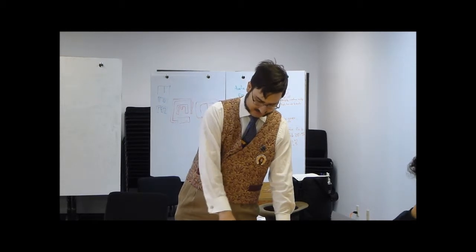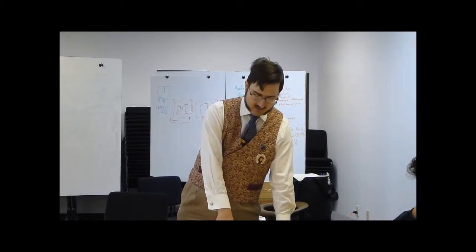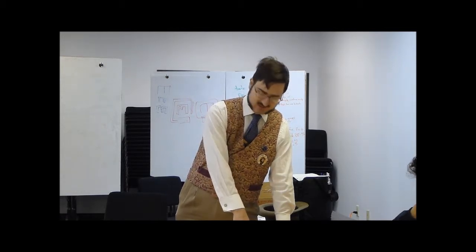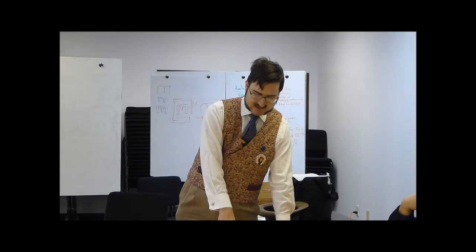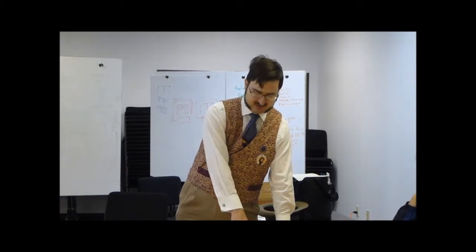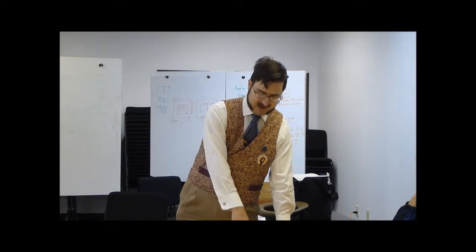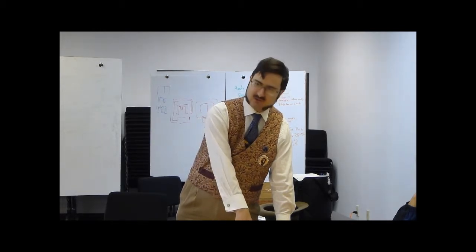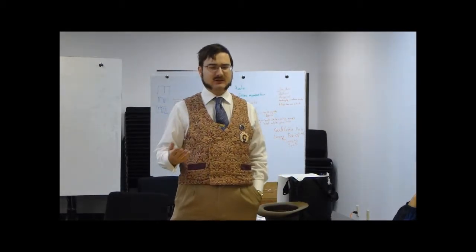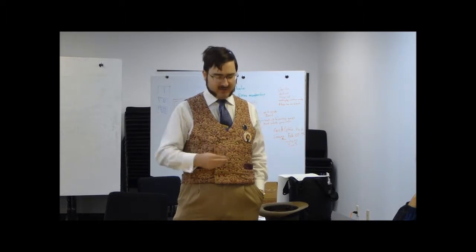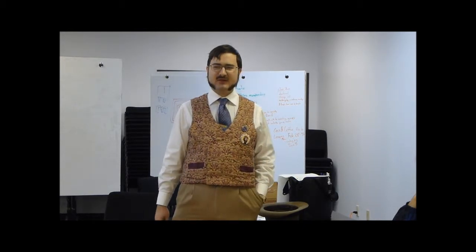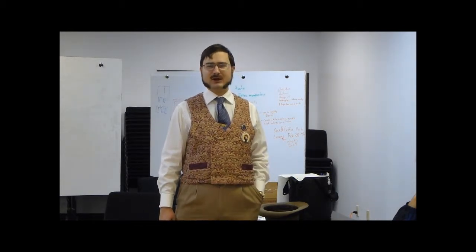And so it takes quite a long time, obviously, but for every 10 of those, you get 1 to this up counter. And so by the time this gets to 0, you've got 100,000 in the up counter, which is, of course, a million divided by 10. And so 100,000 would go to the display. Now, clearly that's not actually practical, the way I've laid it out for you, if for no other reason than that to actually count that down would take 100,000 minutes, and nobody wants to wait that long for a radiation measurement.